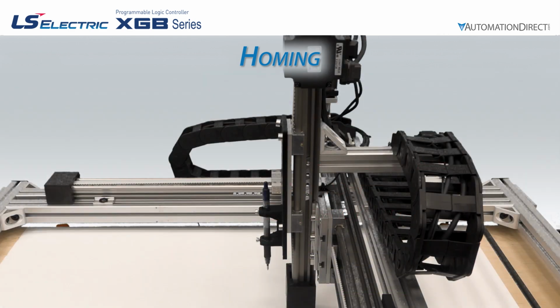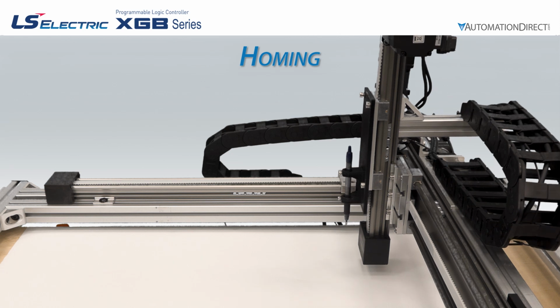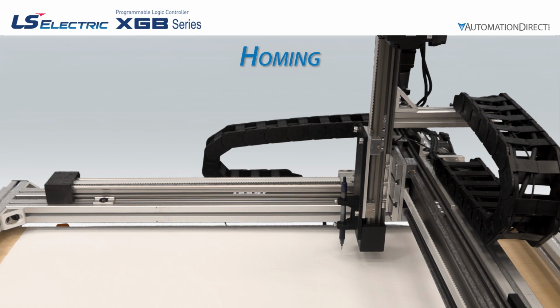Let's turn on our servos and start the homing function for all 3 axes. We see that each axis independently moves in reverse at the home high speed, finds the home switch, backs off at the home low speed, moves forward back on the switch at the home low speed, and then waits for the next command. We have now homed our 3-axis system and are ready for some motion.